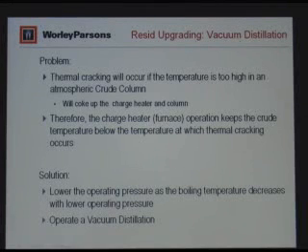So obviously if you go up to a high elevation, like somewhere like Mexico City or one of the other high elevation places, if you boil water, it doesn't boil at 212 degrees Fahrenheit or 100 degrees C. It boils a little bit less because you're at a lower pressure. So the same principle applies in vacuum distillation.